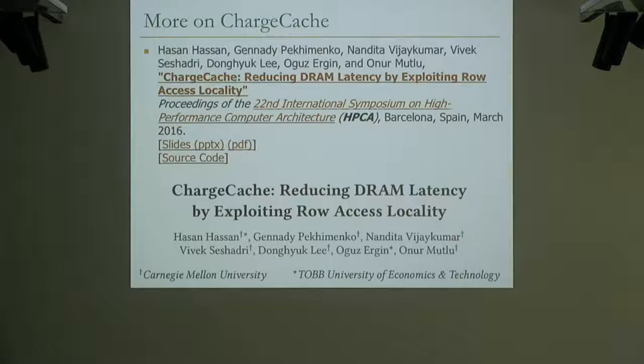Yeah, I think so. So basically, I think this is an indicator that something can be improved in the DRAM system also, but also the cache system potentially, maybe in the prefetching system, right? Because what you're doing here is, the cache system is doing the caching with 64 bytes, and it's doing well actually, but you're really accessing some other cache block in the same row. Maybe if you can somehow figure out which blocks you're going to access, whenever you open the row, you access them, like 4 blocks, before you actually get the request. And then you cache them, and then you don't get another request to DRAM, right?